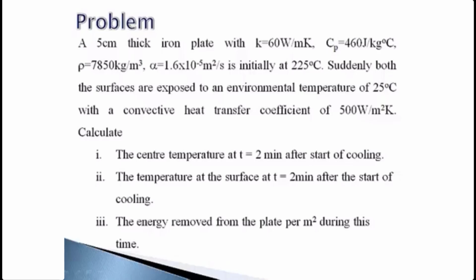Also, we need to find out the energy removed from the plate per meter square area during the first 2 minutes. Now we need to use Heisler's chart in solving this problem. In Heisler's chart, there are 3 charts. First we need to find out the center temperature, that is the mid-plane temperature difference.